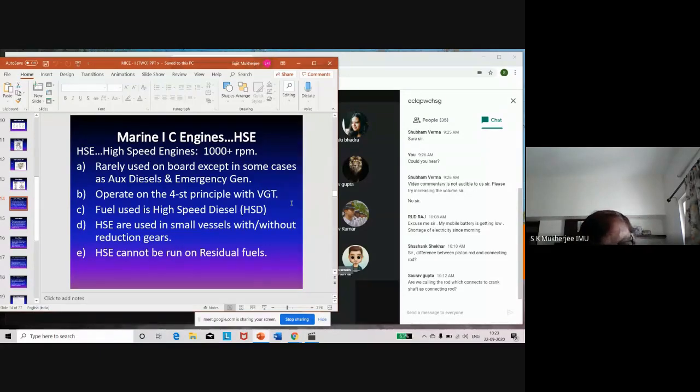Now if it is passing through a large diameter pipe, then the flow rate of the exhaust gas is small. Now if I taper that pipe and make it into a small passage of exit, then the gases passing through that part will be much faster. And thereby, if that is now directed toward the turbine blade, the force to rotate the turbine blade becomes higher.